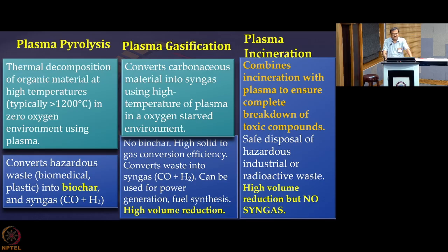So, that is one of the very, very important aspects of these waste to energy technologies. Now, there are three technologies. One is called plasma pyrolysis, another plasma gasification, and plasma incineration. Now, all these are basically burning of waste. Plasma pyrolysis, what it does actually, because of the very high temperature of the plasma that is used, suppose an inert gas, you are discharging argon in some waste, then you are delivering only the heat input.